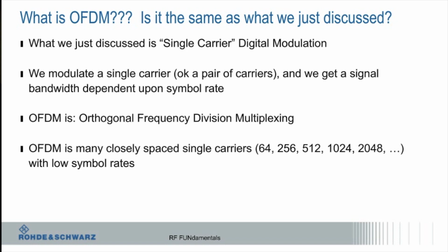But the key thing is it picks the frequencies and characteristics of these signals so that they cannot interfere with each other. They're orthogonal, right? Once I've modulated and all that, they should be completely independent. Just like when I do the I and Q, those signals are in quadrature. So when I put the data together in that IQ stream, the I and the Q can't interfere with each other because they're in quadrature to each other. So this is trying to take advantage of that, but in more dimensions.